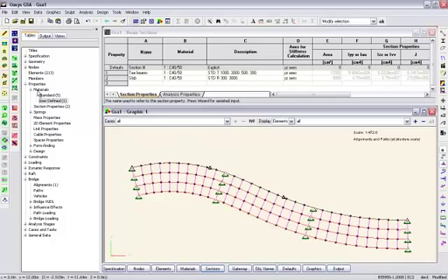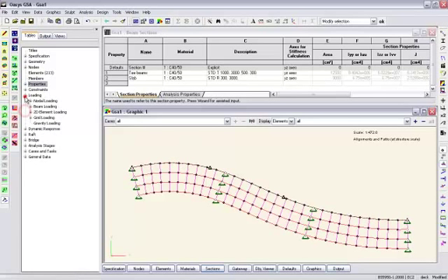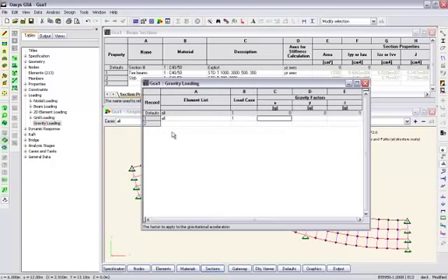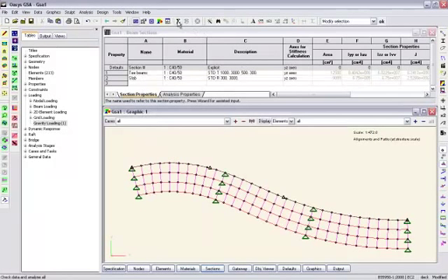Right. Now to check this model's all good, I'm just going to create a gravity load grillage. Half the weight. It's not quite accurate in this particular case, but it will suffice for the moment, because obviously the two elements are not equal weight.